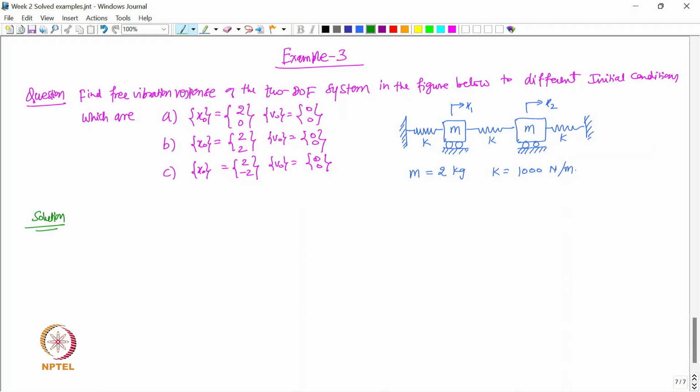So definitely we can now easily again solve the eigenvalue problem and find the natural frequencies and mode shapes, and let us say those are identified already. So solve the eigenvalue problem, right, which gives us the natural frequencies. So I am going to directly write here, that comes as 22.3 radians per second, and the mode shape, the arbitrarily scaled mode shape, is 1 and 1.